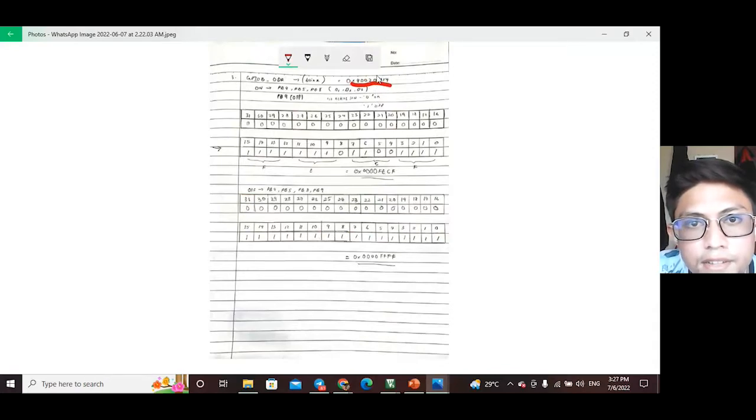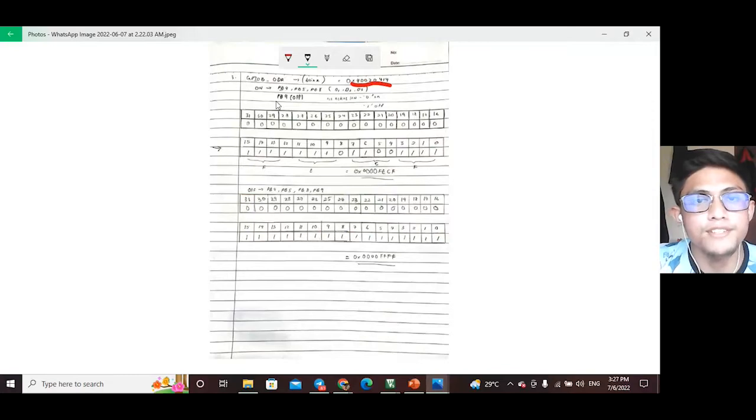This is the constant value and it won't change. We will turn on PB4, PB5 and PB8, and PB9 we do not use, because question one asks us to turn on only three LEDs. Because this circuit is active low, we will put 0 as on and 1 as off.